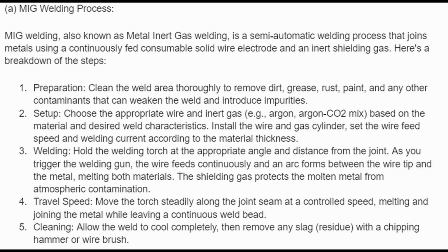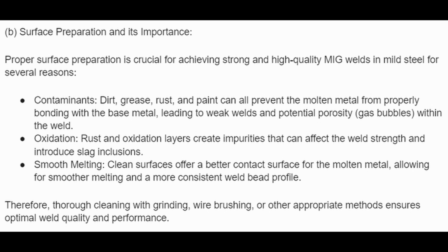5. Cleaning. Allow the weld to cool completely and then remove any slag residue with a chipping hammer or wire brush. B. Surface preparation and its importance. Proper surface preparation is crucial for achieving strong and high quality MIG welds in mild steel for several reasons.